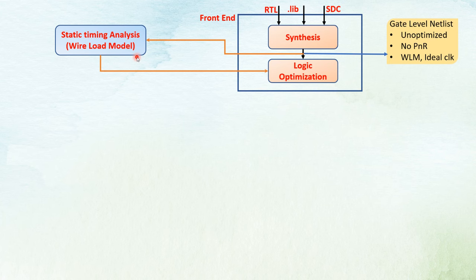While estimating, it estimates the electrical delay and capacitance associated with the on-chip interconnects, such as metal wires connecting to different components of the standard cells within the integrated circuits. It's an essential component in the analysis of signal propagation, delay and timing analysis of the digital circuit.